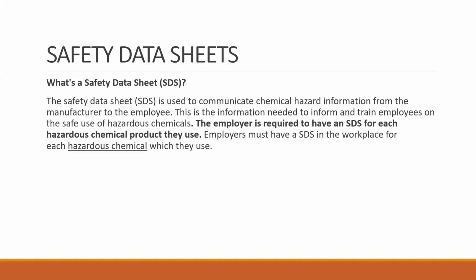In the laboratories, the laboratory staff are using the chemical, and the data sheet is in the computer of the quality manager who is absent today. These kinds of issues are highly unacceptable. They are high level violations of the OSHA standard. So whenever you are using a hazardous material or chemical, the MSDS should be available at the point of use, which means at the same workplace.